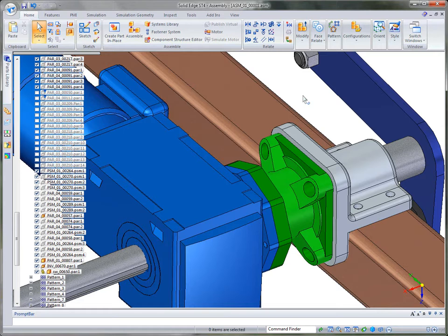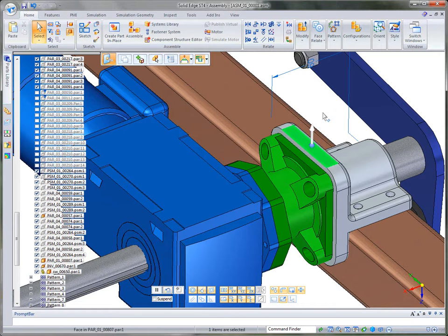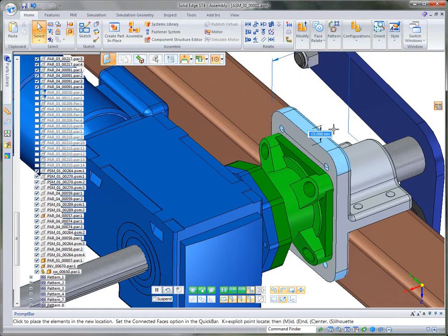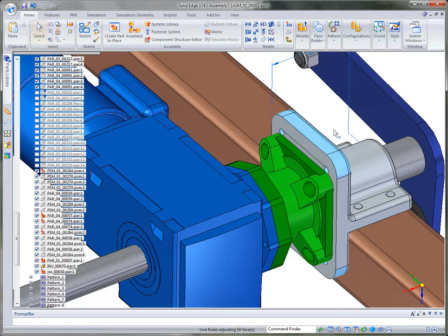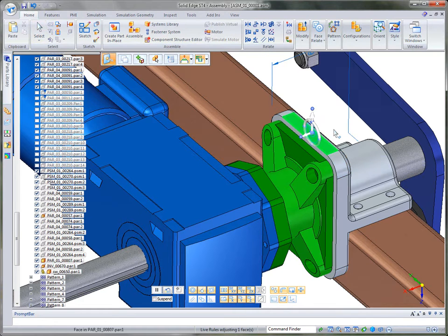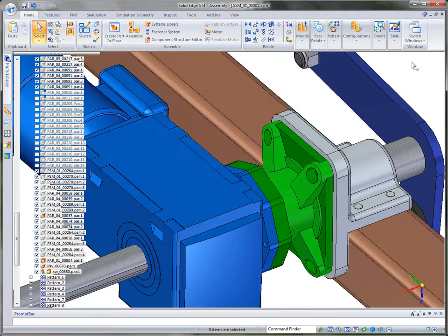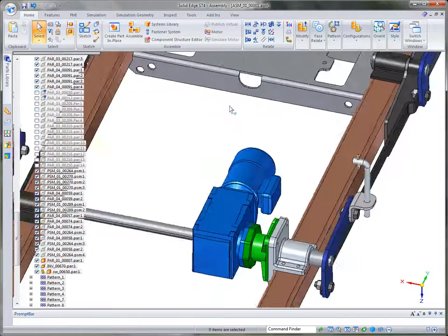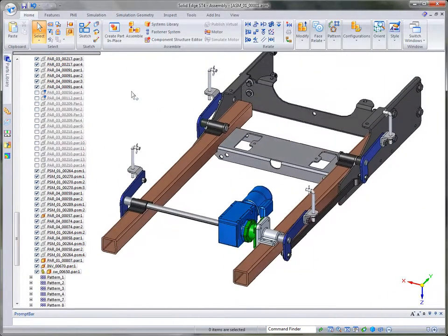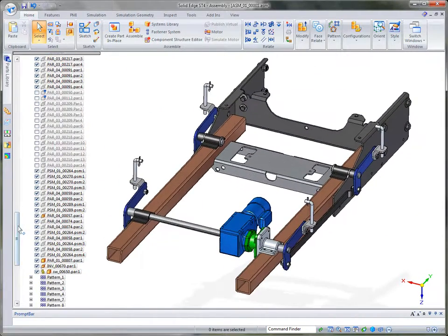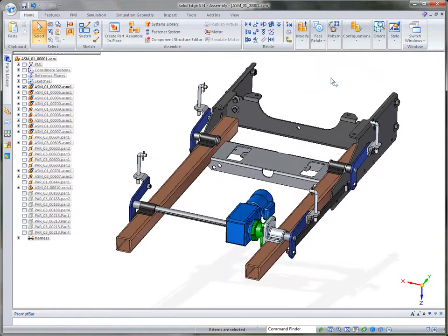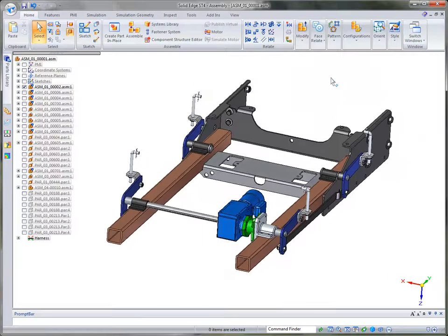And then you'll notice if I go to a face select and actually pick this face, when I move this face up, let's say I move it up 10 millimeters, notice the green part will respond because of those concentric relationships that were just created and automatically place that file or adjust that file to the proper relationships. Now once we're done with this, you can see that there's a lot of power in Solid Edge ST4 Synchronous by using direct translators and bringing 2D to 3D.